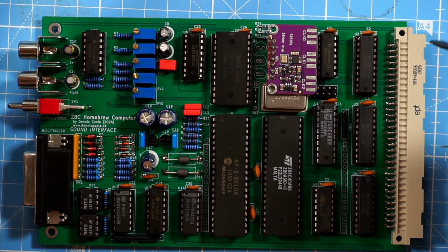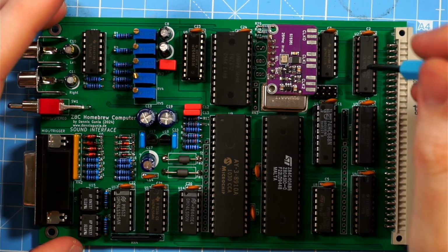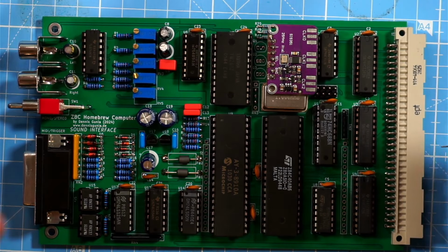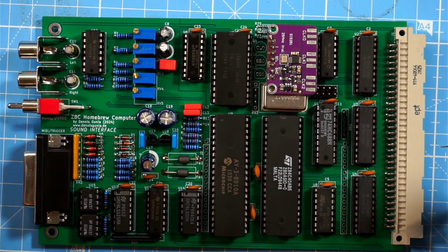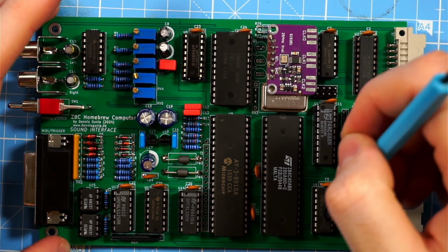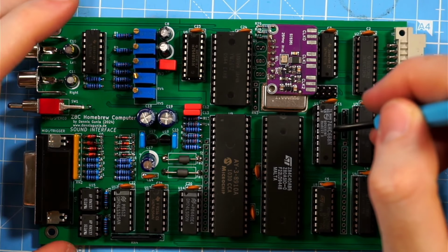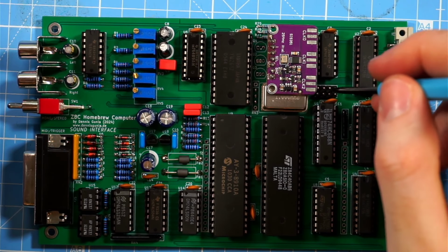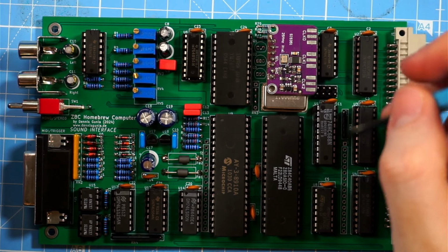Starting on the right, I have the bus connector right here, the backplane connector, and bus transceiver ICs for buffering the bus, so not all ICs are connected to the bus, and the CPU doesn't have to drive them all. I have some logic chips right here for address decoding and stuff like that. The 74HC688 does the address decoding, so I can set an address for this card. It's the upper 4 bits, and the rest is then decoded by the